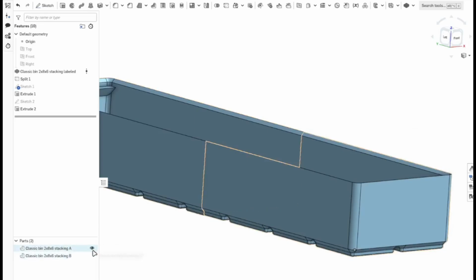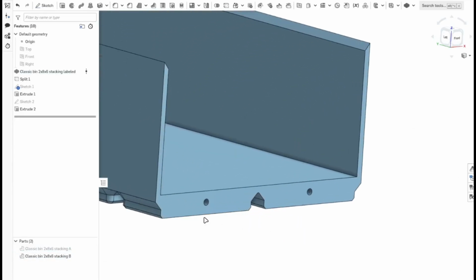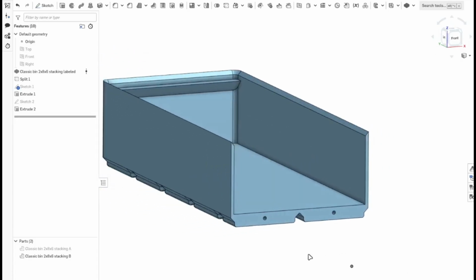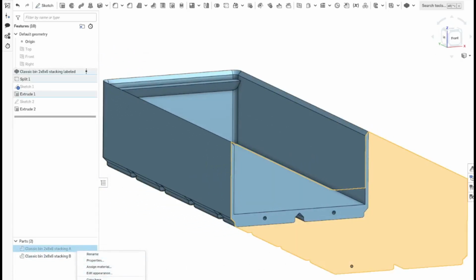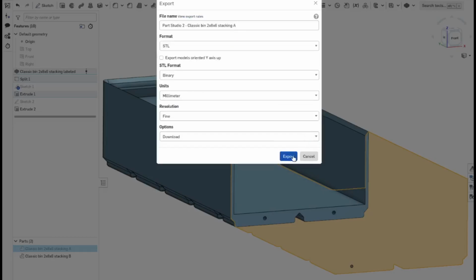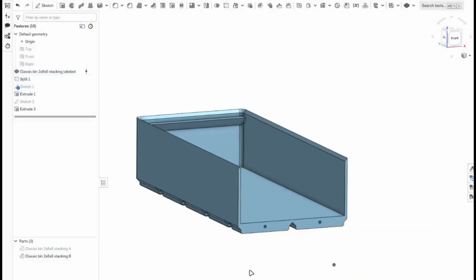So once you print this, the 2 holes will match and you can put your 1.75 mm leftover filament, which you have. Ideally, you can use PETG or ABS, but not PLA. PLA is brittle; it will break if you use that. So I would recommend going with PETG, ABS, or anything else. Once this is done, you can right click, export, and then you can select to print this. So this is one way of doing it.